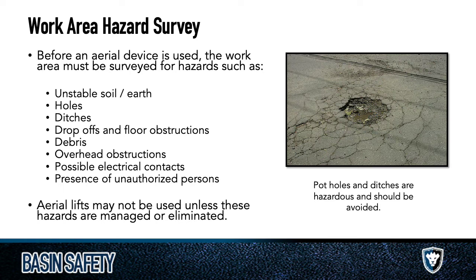What I've seen in all the white papers and stories I've read, fortunately I haven't been to too many incidents with these, is people operating them in unsafe conditions, near power lines, driving too fast with the basket elevated, and they hit something, a bump, and they're not tied in, and then they fall out of it. Those are the instances, or on unlevel ground, and it tips over. Those are the things that happen. So don't be afraid of the equipment.